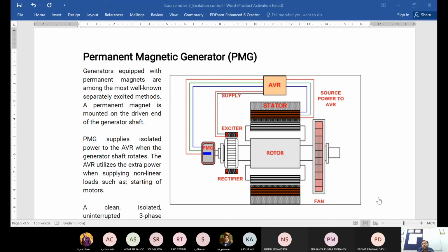Some of the major blackouts have occurred across the globe, many times in India also, but the most famous one is the blackout in USA, because it was at a very big level, and because it happened in USA, the entire world took note. That 2003 US blackout was almost half of the United States grid collapsing, the eastern half basically, and it was triggered by a voltage collapse due to inadequate reactive power in the system.